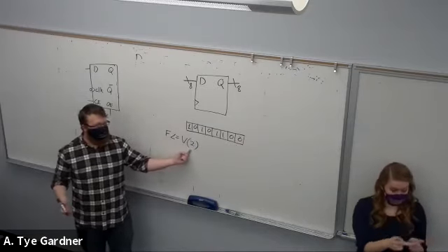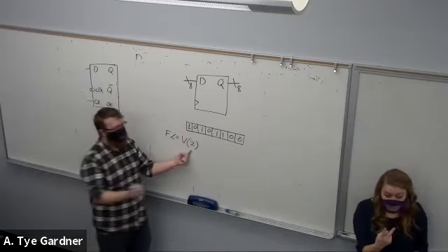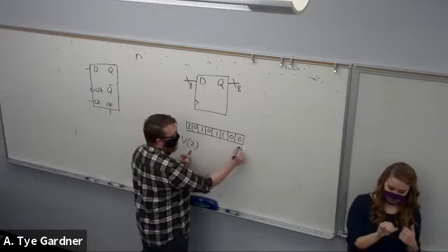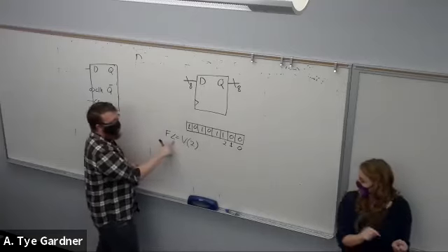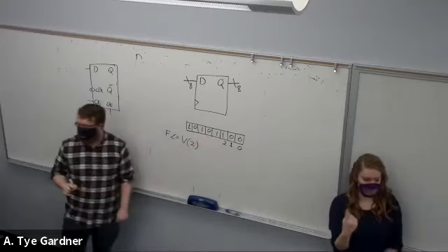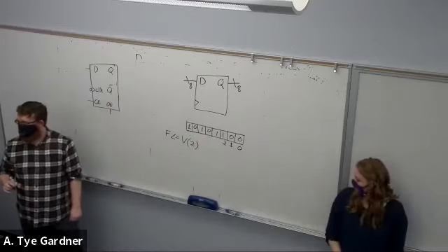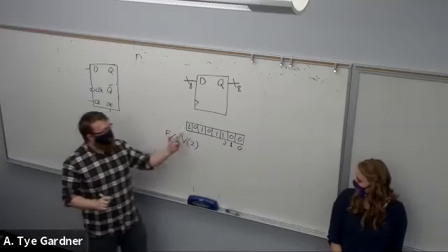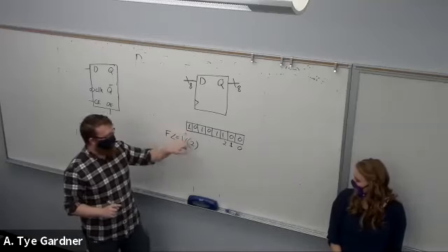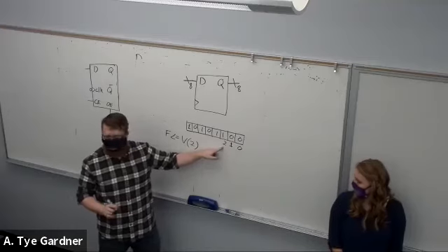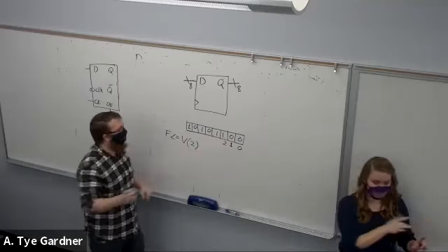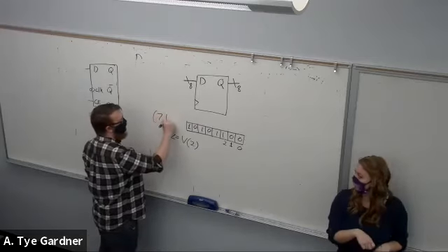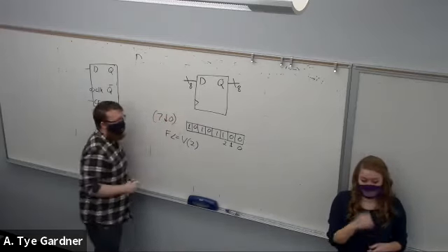And location 2 is, well, we're 0 indexed, so that means the furthest right one is 0, 1, 2. That means in this case, F is 1. It would be flipped if it were otherwise. So this is the case of 0, 1, 2, right to left. That's how we tend to think, right? This is the case when you use the 7 down to 0 notation.